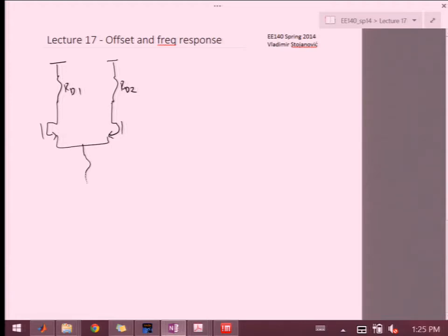there are also implications on these two values, which are, we said that in a well-balanced circuit, the gain between common mode and differential mode was 0, simply because everything was nice and symmetric, right?